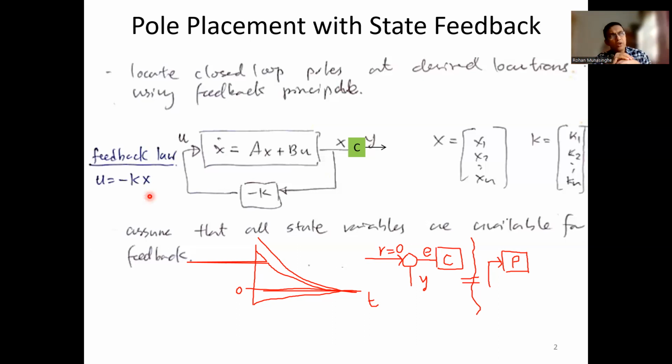All right. So if you have a very good plant where tracking performance is good, its regulator performance is also very good. In fact, you design the regulator problem, get a better result from that, and then you can put it into the tracking problem. Okay, so I think so much for that. We can move on. So I think we have no problems as to why we close the loop this way without the reference. And also our control law u equals minus Kx is logical.